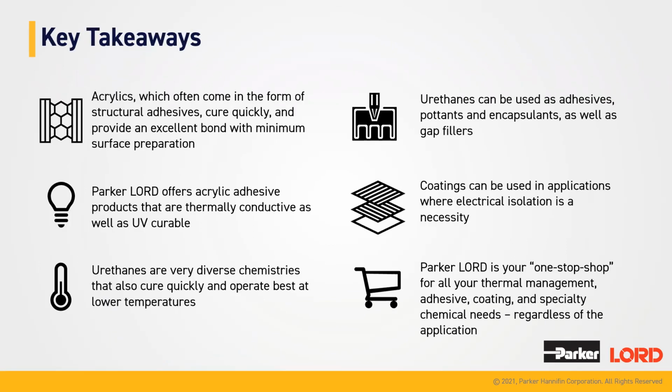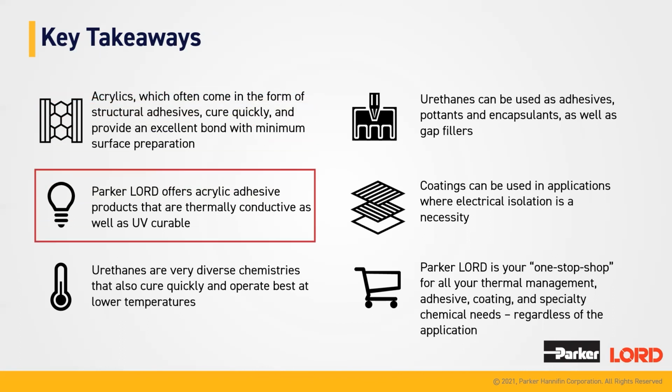So to tie everything together, some of the key takeaways from this presentation. Acrylics, which often come in the form of structural adhesives, cure quickly and provide an excellent bond with minimal surface preparation. It's also worth noting that Lord does offer a thermally conductive acrylic structural adhesive. Parker Lord offers acrylic adhesives that are also UV curable.